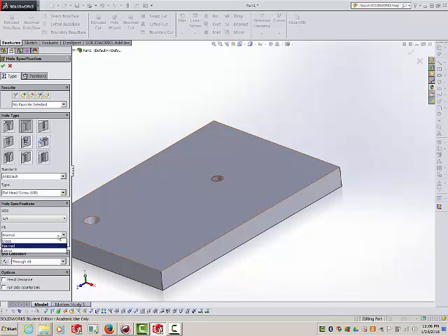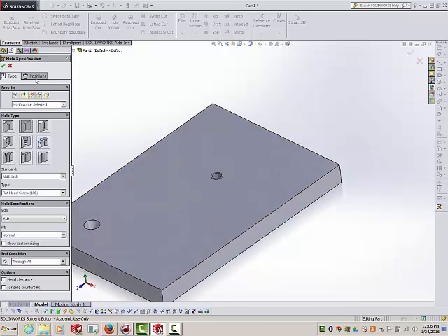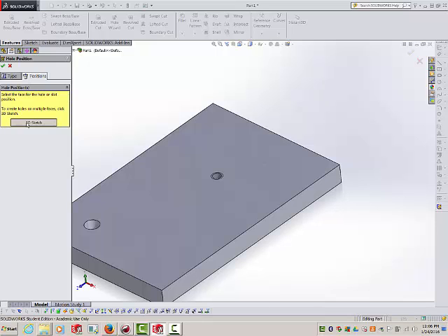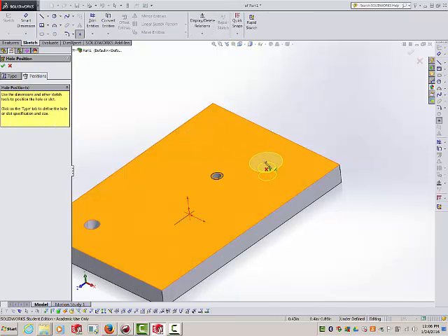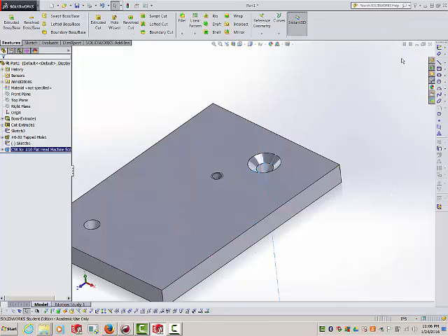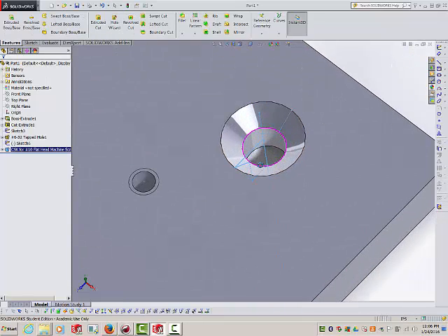I could do normal, close, or loose fit. I thought I did number 10. We could do a quarter inch or number. I'm going to do a number 10 screw. We could do far side countersink, head clearance, and let's go to positions. And let's activate my sketch, and I will grab that point location, and basically we're done. And we've got a